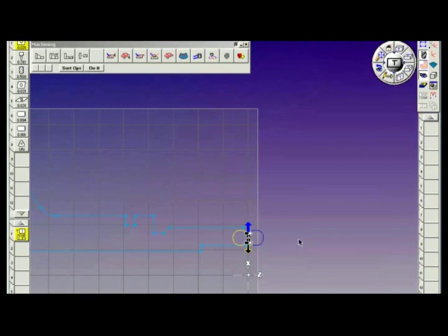The markers appear, and I'll take a moment to explain the markers. The markers appear anytime you select a feature. Anywhere you click, you'll get your machining markers. If you want your markers in the midpoint of a feature, simply click on the feature, hold the control key, click off the part, and the markers will snap to the midpoint of the selected feature.